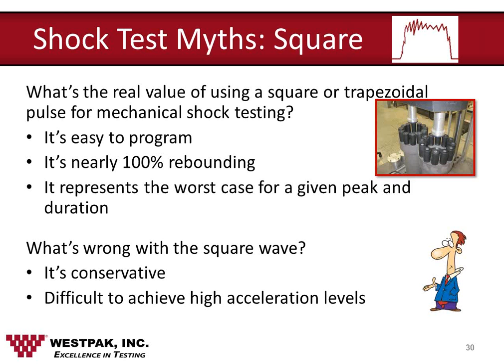Given all the pluses and minuses of this so-called trapezoidal pulse, it still represents the best and most uniform approach for shock fragility testing. Interestingly, even though Mil Standard 810 incorporates the trapezoidal pulse as a standard shock test method, it's still not widely utilized in military test applications. Since much reliability testing had its origin in mil-spec applications, common reliability testing somewhat shuns the use of this trapezoidal pulse, although the trend is diminishing.